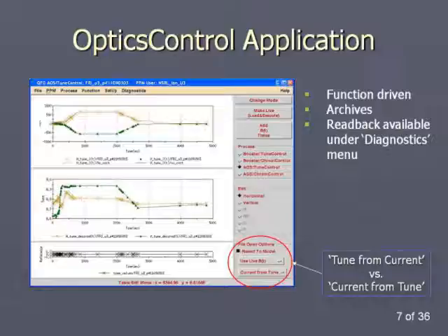Vincent, hang on, before we go. No, you don't have to even do that. I want to make sure everybody knows though, so in the booster, the main magnet power supply is connected to the dipole and the quads, one set of windings. Then the optics controls the tune supplies, which are extra windings on the same quads, right? In the AGS, the dipole and the quads it's a combined function magnet, right? So the main dipole is connected to the main magnet power supply, and that's it. This then controls extra power supplies which are connected to separate quads. Okay, that is a distinction.